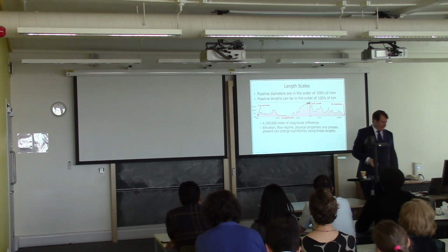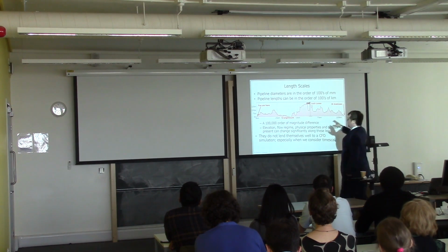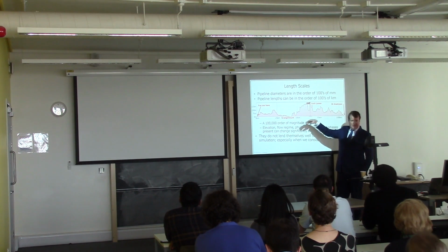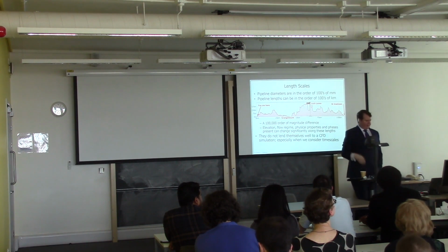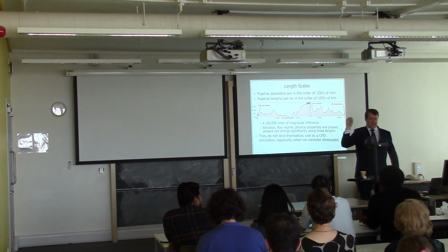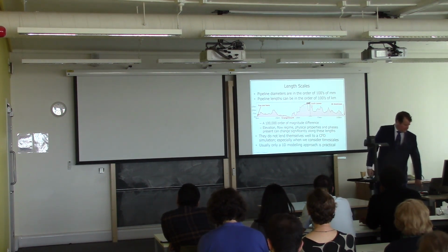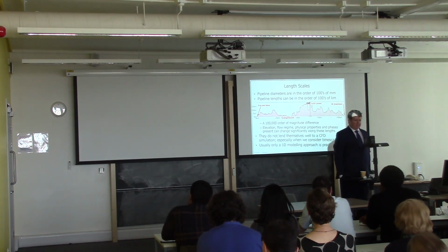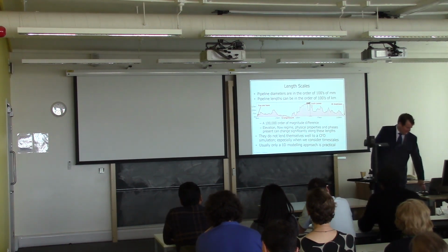So it doesn't naturally lend itself to the CFD simulation, particularly as we want to model the whole pipeline, because things are changing along the length, the elevation's changing, the number of phases that are present can change, the temperatures, the physical properties, flow regimes, things like that can change along the length. So I really do need to model the whole length. I can't just model 1 metre of this and extrapolate. So as I say, it doesn't lend itself nicely to CFD simulations. It's typically what we call 1D models. If you're familiar with that, good. If you're not, I'm not going to explain it to you. I don't have enough time.